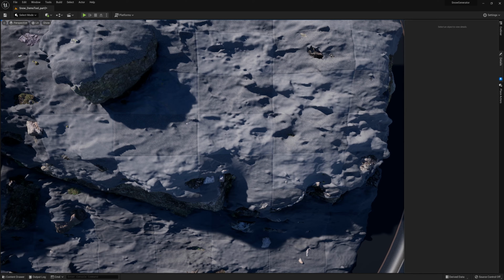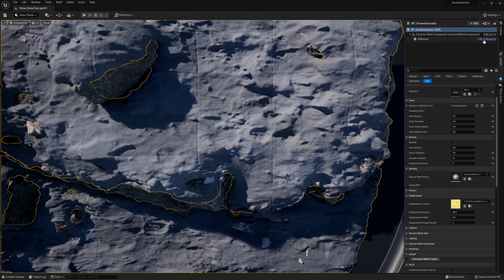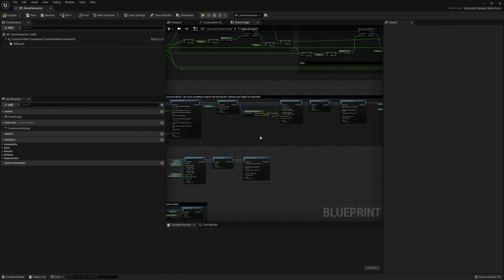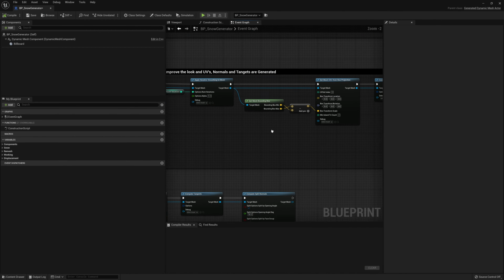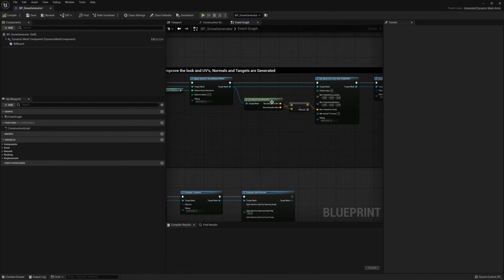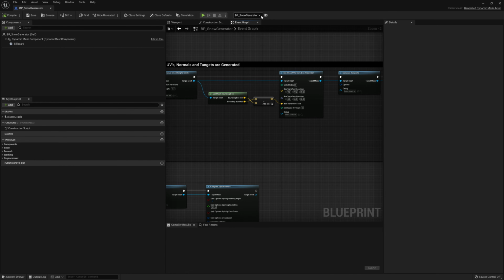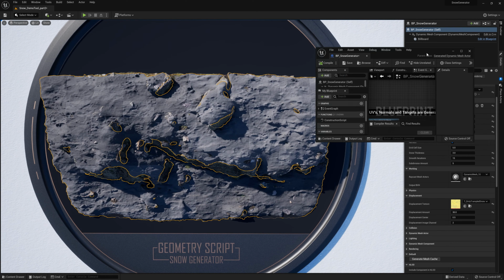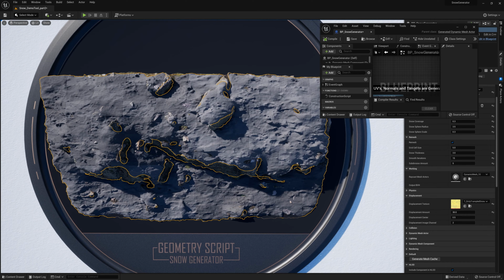So the way we're generating the UVs currently is not ideal. So I'm just going to go in and quickly fix that. There's 2 things that I would like to do that will help resolve this issue. The first is that what we're using is the mesh bounding box, and we're taking its minimum values in the X, Y, and Z and using those to create our UVs. So basically what we're doing is, even though this is a rectangle, we are stretching this to take up the full UV space, which ends up meaning that we distort the shape. So we don't actually want to do that.